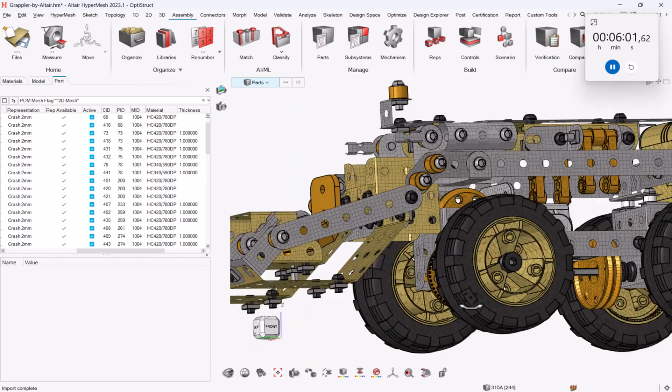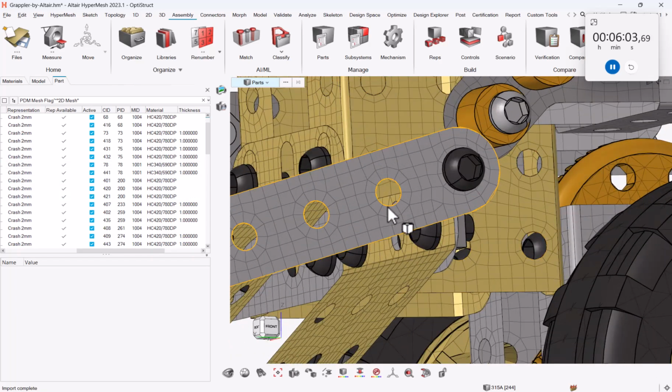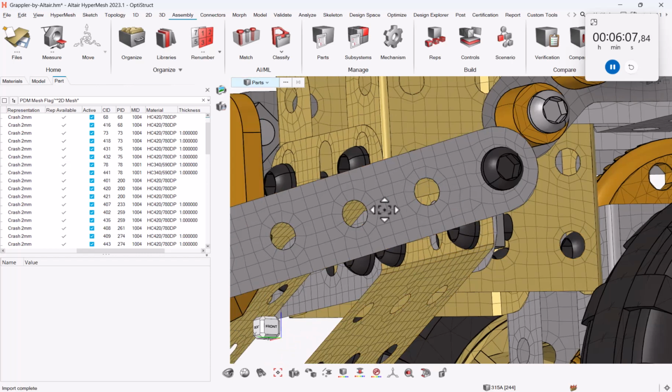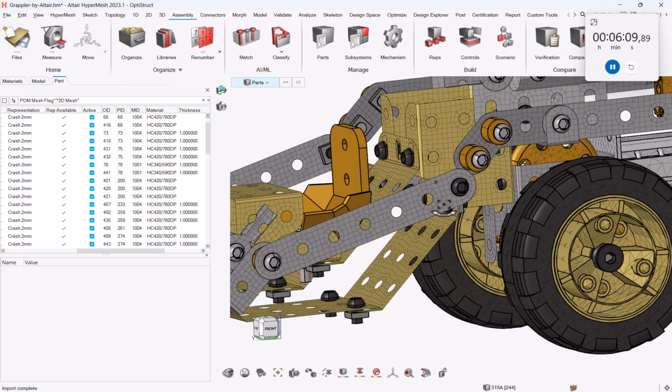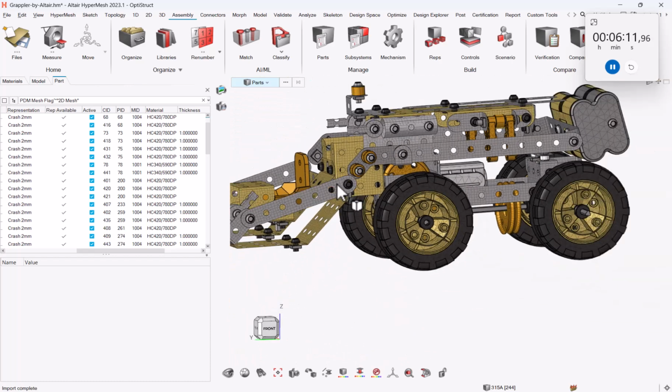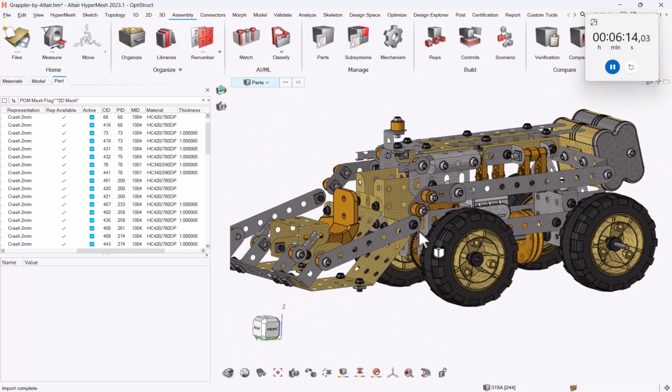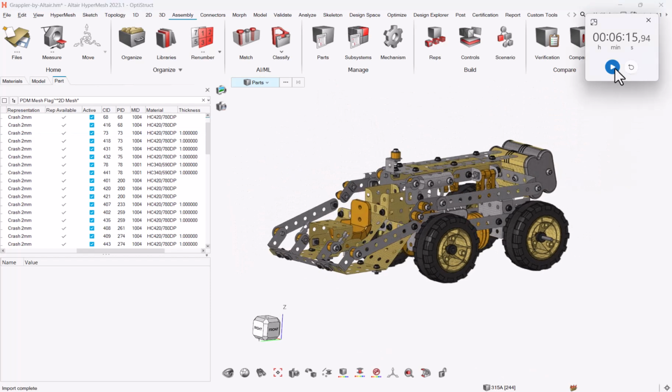If we look at other parts, you can see that in our parameter criteria file, the settings were done in such a way that there is a washer around every hole. We have something which is quite regular, so this is quite a nice mesh. Within, let's say, 15 to 20 minutes, I was able to get a first mesh done for all my Tetra mesh, all my Hexa mesh, all my 2D mesh.